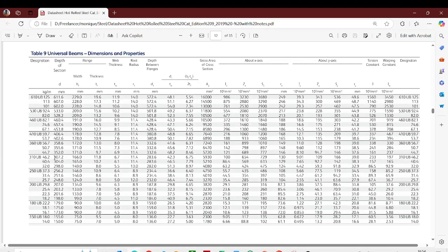After that we need to find out the maximum section modulus. To find out the maximum effective section modulus, we need to find out what is my lambda suffix e, that is nothing but b over t square root of fy over 250. We need to get the dimensions b, t, fy for web as well as flange. So let us find out these details. I am referring to the data sheet. So this is the data sheet given.